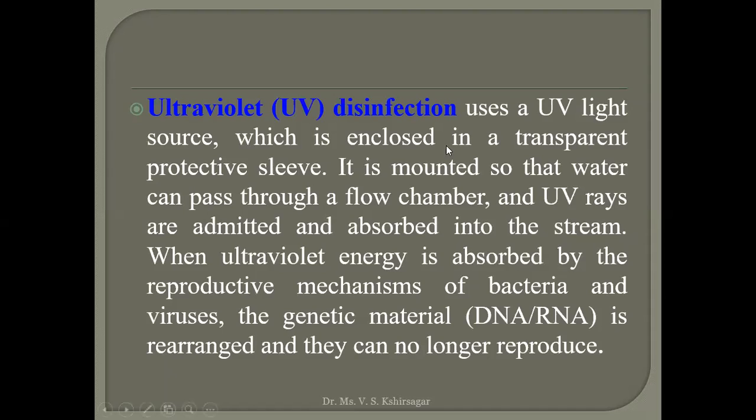A very big advantage in respect of bacteria killing by using the ultraviolet radiation. But equally, the same problem as mentioned in the ozonation. In the ozonation, we saw that a huge amount of investment is required for the separate attachment to convert atmospheric oxygen into ozone.